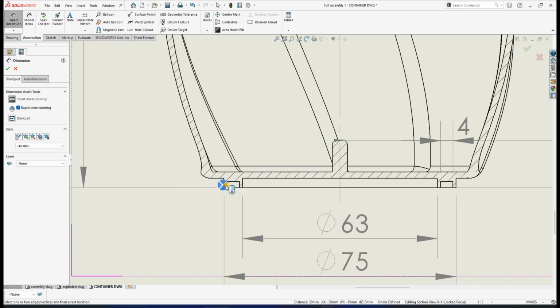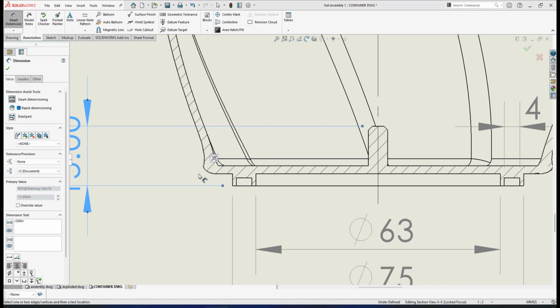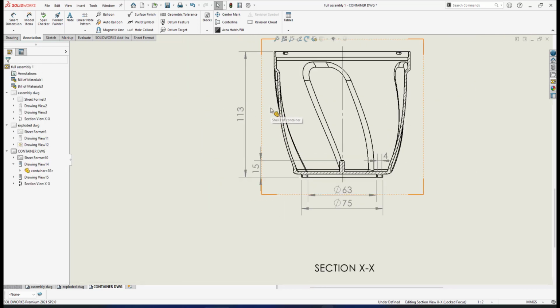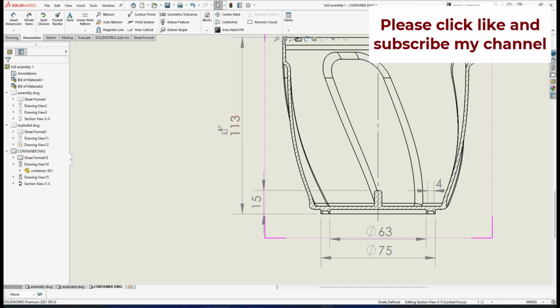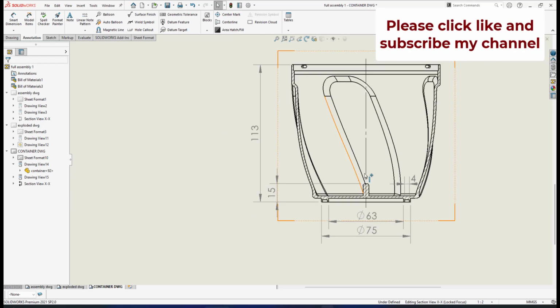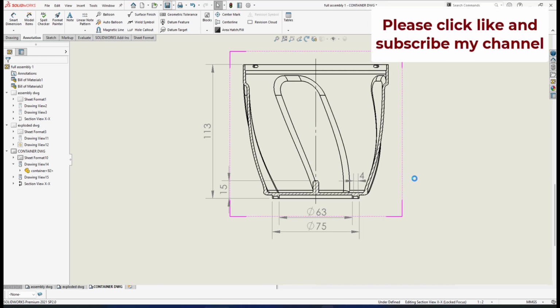Okay, if you look here, we have the icon, we have 4 options: top, bottom, left and right. So this one I will go to the right position. If I click OK, then this one is none for not 2 decimal points. Automatically SolidWorks, as you can see, the dimension for the main height 113 is shifted to the second level, so the distance here remains 3 millimeters. So let me save my file again. So this will be our next dimension.